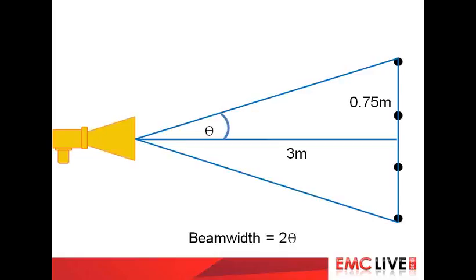This zone of interest, if you look at this picture, we're now looking at the calibration plane from the side, and we can see those 4 points from the side, and we can see the antenna. And our area of interest is the area that illuminates the top point and illuminates the bottom. Anything outside of that, above or below the uppermost and the lowermost point, we don't really care about. All that's going to do is be absorbed by the chamber walls or bounce a few times and then eventually absorbed. What we're interested in is that zone of interest, the calibration plane.